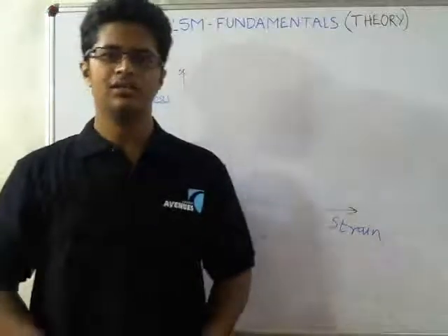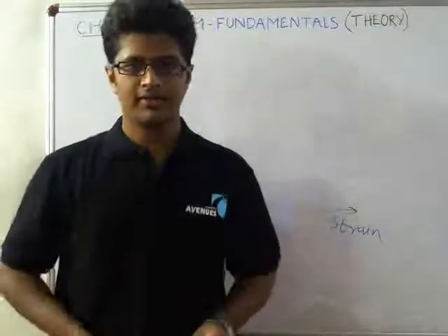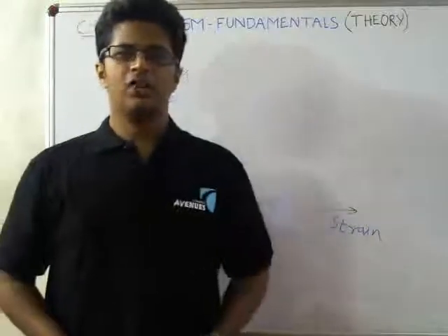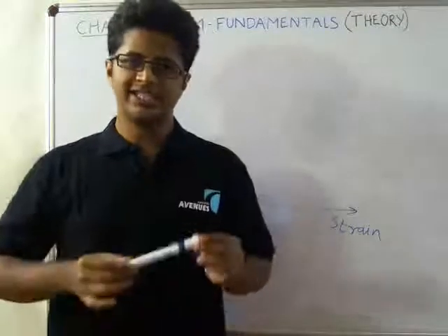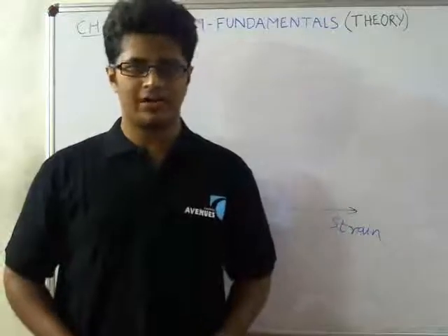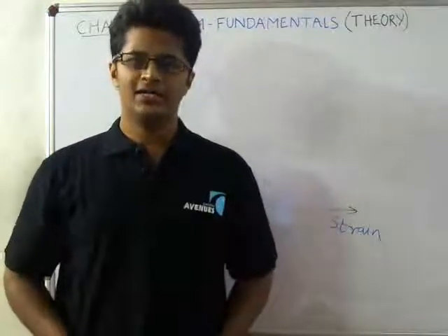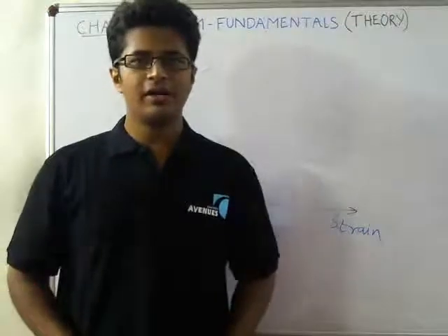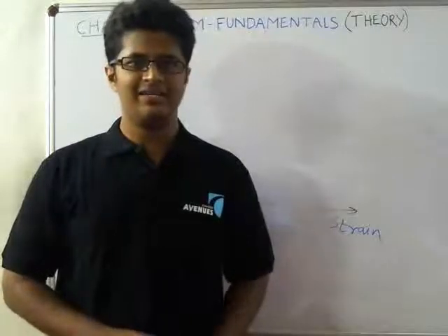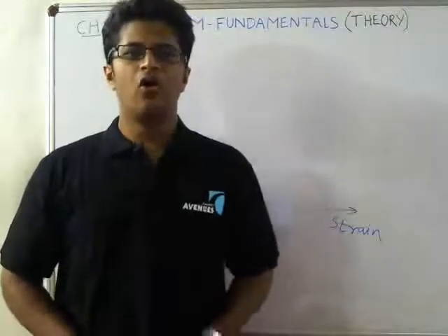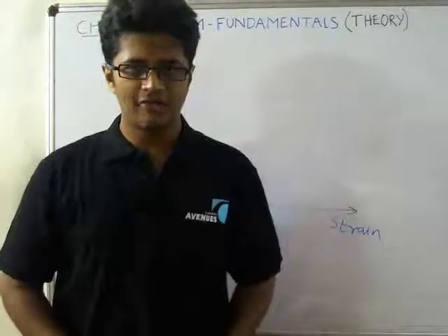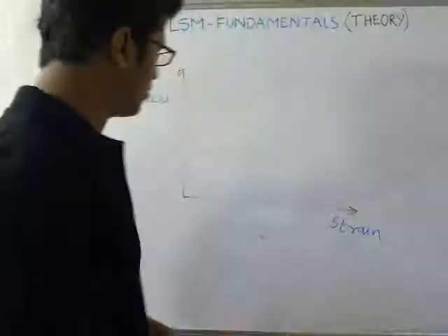Now I am going to draw the same graph for concrete. One thing has to be understood: for the mild steel graph which I had drawn, we have already done the experiment in order to obtain it, and almost every time we obtain a similar sort of graph. But in case of concrete, things are different. The graph of concrete is very complicated with respect to other graphs like that of mild steel. In order to avoid such complications, IS 456-2000 has given a separate graph for concrete, which I am about to draw.